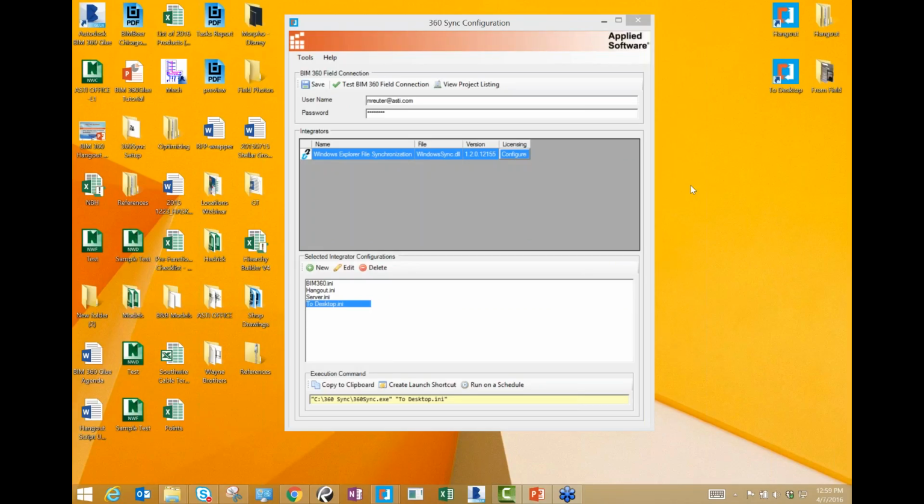And the answer to that is no. Bluebeam hyperlinks work if you were to upload manually into BIM 360 field. I have been seeing some issues where some older versions of Chrome may not accept some of the hyperlinks, but for the most part, if you create hyperlinks in Bluebeam, then they work in BIM 360 field, both on the iPad and on the web.